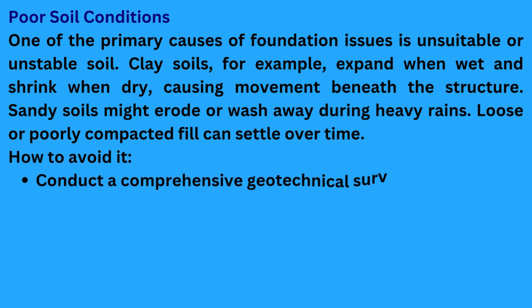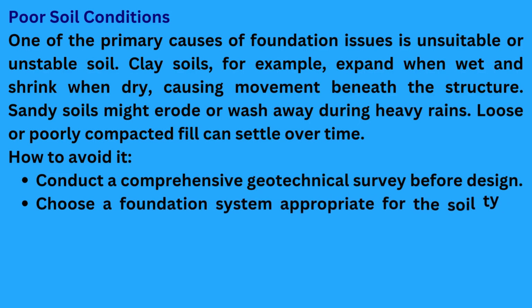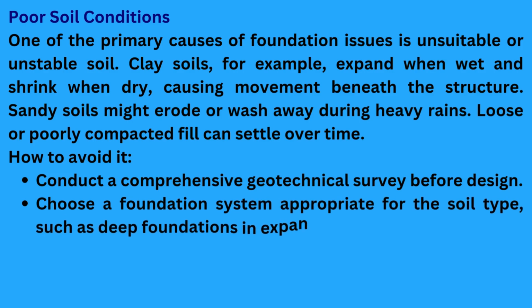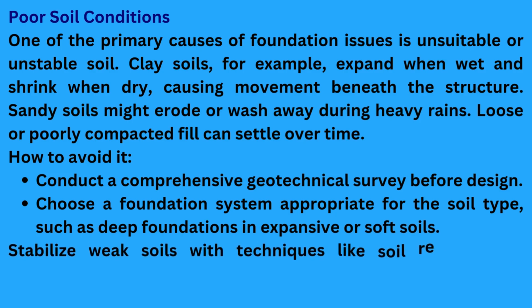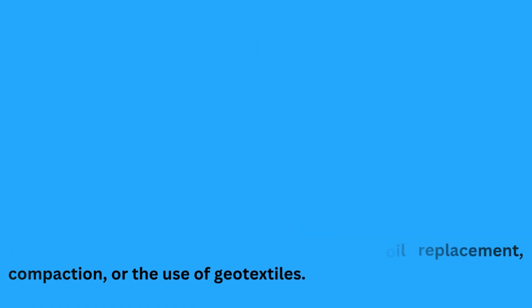How to avoid it. Conduct a comprehensive geotechnical survey before design. Choose a foundation system appropriate for the soil type, such as deep foundations in expansive or soft soils. Stabilize weak soils with techniques like soil replacement, compaction, or the use of geotextiles.